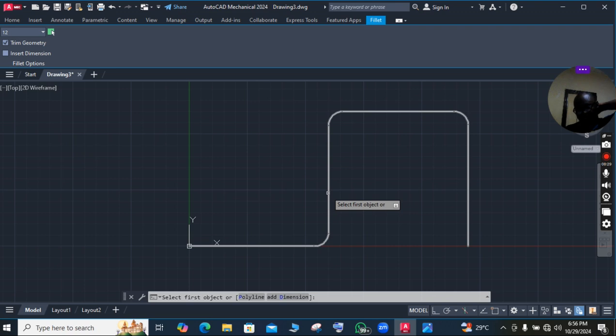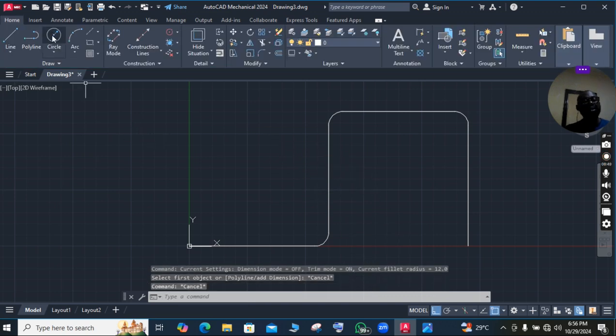Now the next thing, we shall extrude a circle along the path of the polyline. This will be one way of drawing pipes in 3D. So I will come and pick a circle.